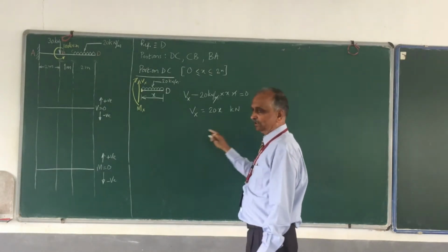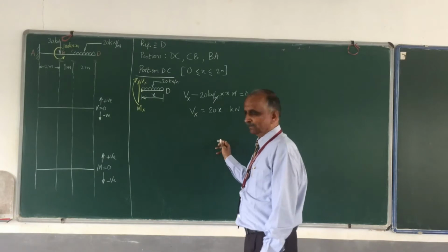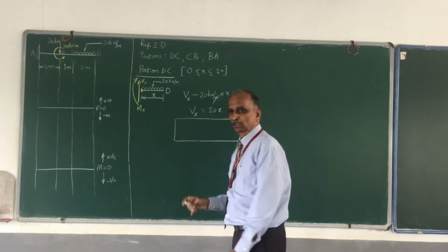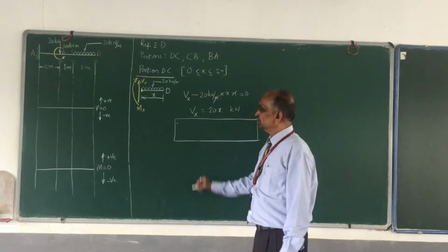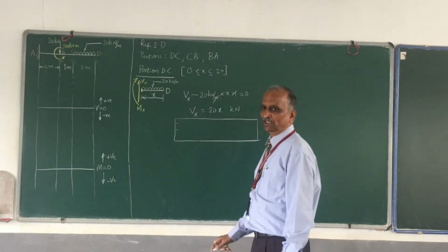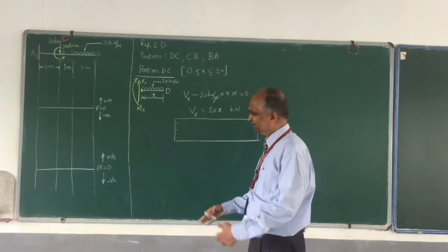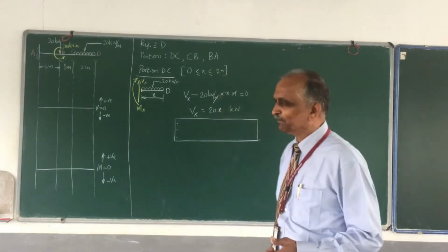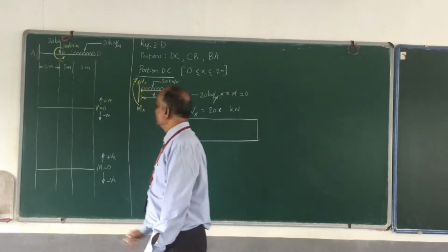Okay, the shear force is not constant between D and C. So it is varying. These are the observations. I want you to write it here. I am leaving it to you. What is the first thing? Shear force is not constant between D and C. Shear force is varying between D and C. The variation is straight line variation, or what is called linear variation. I want you to write these three observations. Maybe after some time you will make these observations mentally and you can skip writing them. So initially practice that. Let me go back and complete the shear force diagram.